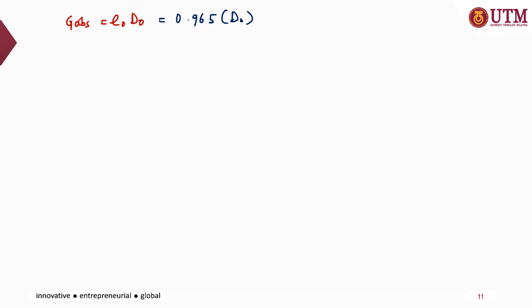So now we need to figure out what D naught is. D naught is the maximum directivity, from last week's slides. D naught is equal to 4 pi multiplied by U max, the maximum radiation intensity, divided by the radiated power.